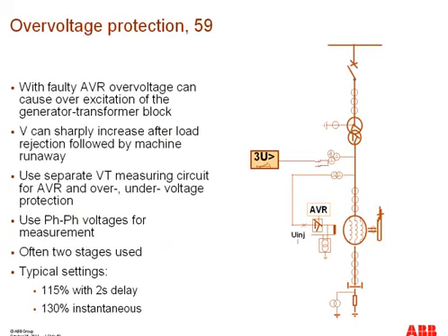Typical settings are 115% with 2-second delay and 130% instantaneous. This function can also be used for open-end detectors or switching on and off of reactors or capacitors when combined with the directional reactive power function.